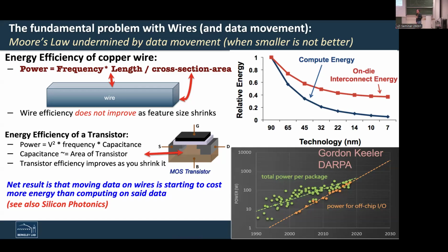That's what we end up doing. So you end up curtailing bandwidth by lowering the frequency that you operate the interfaces. That saves you power, but curtails your bandwidth. So it's a constant trade-off. Where do I want to shift the power?